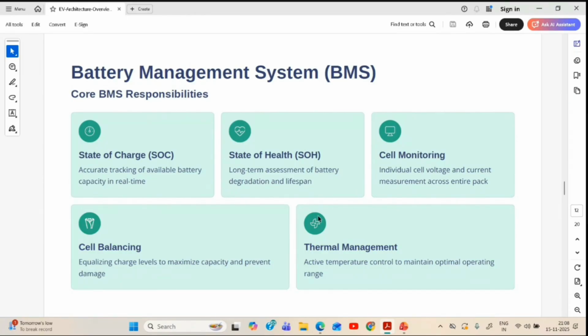So why is this particular domain so difficult? Because understanding of these things is also very difficult. You will not find any proper source to know all these things, right? Okay. For some advanced concepts, for example, we are using Kalman filtering. So how is this Kalman filtering used, how to develop it, and what parameters do we use? Next is your SOH. SOH also uses electrochemical impedance methods, spectroscopy methods, all these things are there.